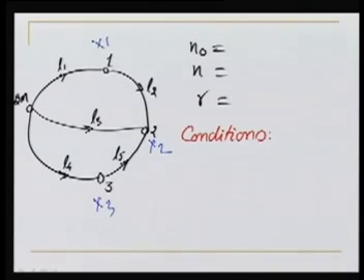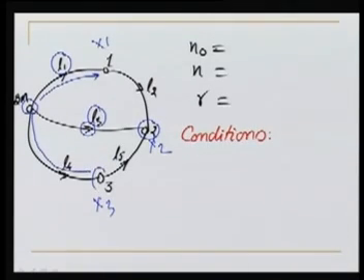Well, you can guess very easily. Starting from the benchmark, I can take this route, I take the observation L1, so I know the RL of point 1. Similarly, starting from the benchmark, I can take this route and determine L3, I can find the RL of point 2. And finally, I can take this route and determine the RL of point 3. So there are only 3 observations.